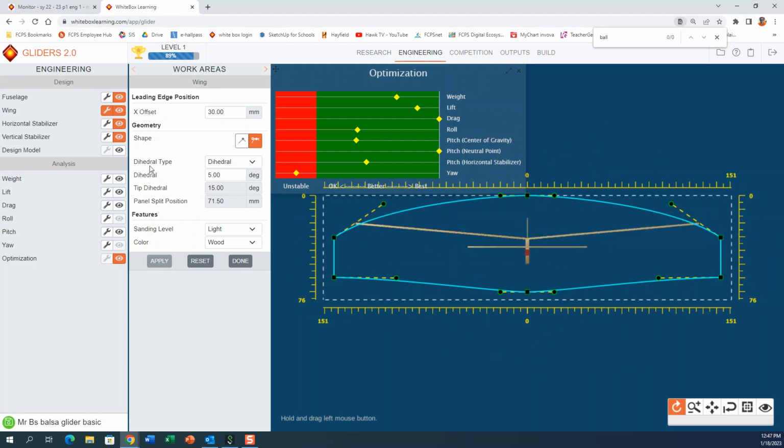They are not flat. I'm going to go ahead and set that angle to 0 to show you what flat looks like. Okay, that's flat. Boom. And notice what happened to my roll when that happened. My roll tanked, okay? It got really bad. No planes have flat wings like that. Maybe some of the real old ones did because they hadn't figured this out yet. But, okay, so let's put it back. I think it would default it to 5 degrees, okay?